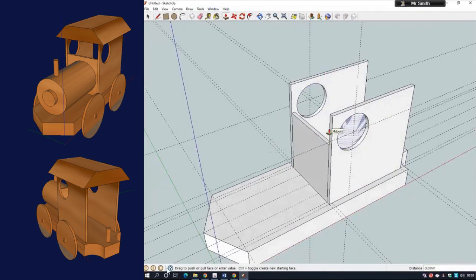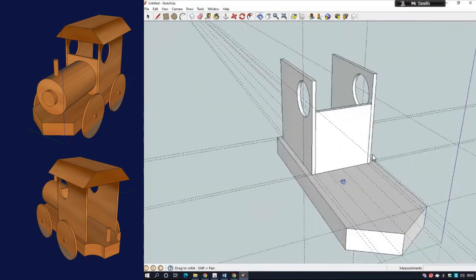If you're struggling to push pull, what you can do is click on the object and then hover over the depth you want it to be, which would be this back line. You notice how deep you want it to be. Watch this. I go to the push pull tool, click on the object, and then hover over that point, which is where I want it to go to. It knows how far through I want it to go.